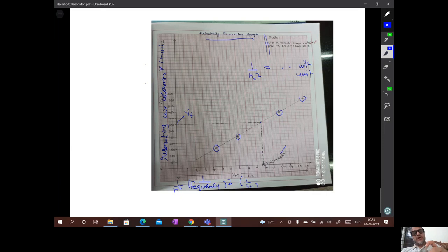When the air pushes out, it goes some distance, then by the time the pressure decreases in the cavity, the outside air molecules push it back, right? So this is like a simple harmonic oscillatory motion, and the frequency of that vibration is what you listen to when you use the bottle as a Helmholtz resonator.